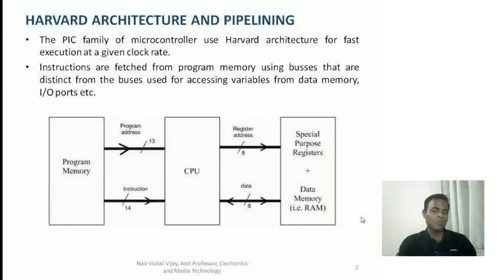So it has a separate program memory, it has a separate data memory, and it has distinct buses for fetching program data as well as RAM data. So this makes the execution of the program faster. That is the concept that is being used in PIC microcontrollers.